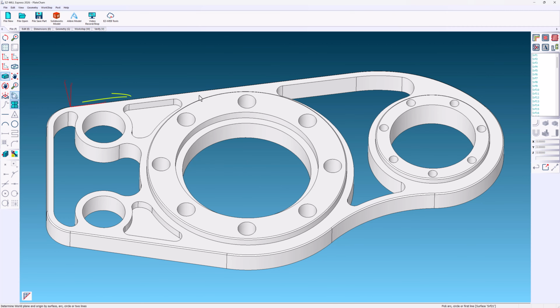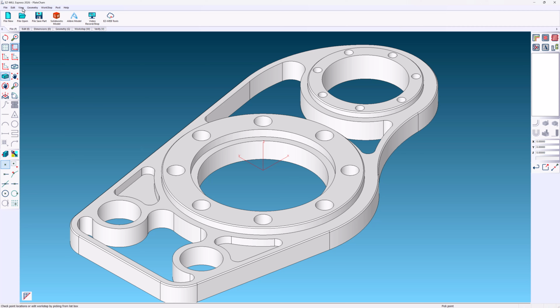The x-axis is snapped lengthwise on the face. The center of holes are also an option. Let's take a quick look at World on 3 points. As you can see, the UCS is floating on the screen. Switch your pick point to all so you can snap to the center of holes and points of lines and so on.